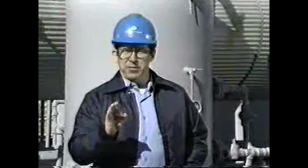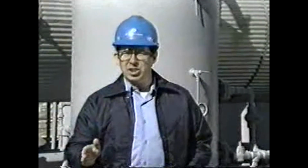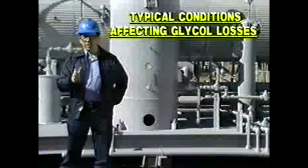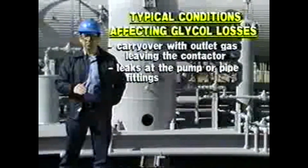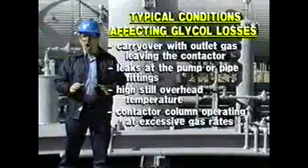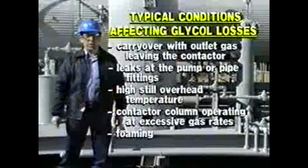To really operate efficiently, you've got to minimize your glycol losses. Losses occur due to vaporization, entrainment, and mechanical leaks. Typical conditions which affect glycol losses include carryover with outlet gas leaving the contactor, leaks at the pump and pipe fittings, high still overhead temperature, the contactor column operating at excessive gas rates, foaming, and rapid changes in the gas rate.